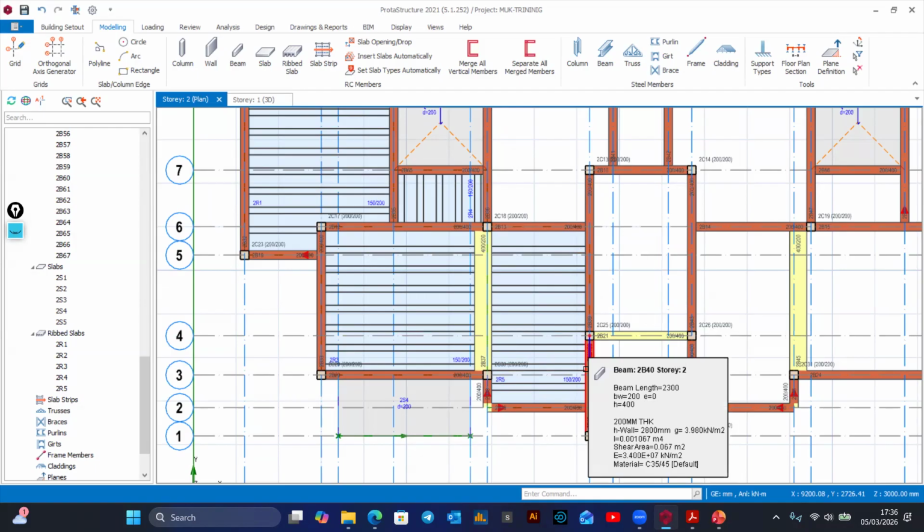You're going to design it and it keeps failing. And once the slab beam is failing, the only alteration that you have to do is just changing the depth. Rather than changing the depth of a slab beam, you design a drop beam. But if you are constrained to that, then you change the orientation.